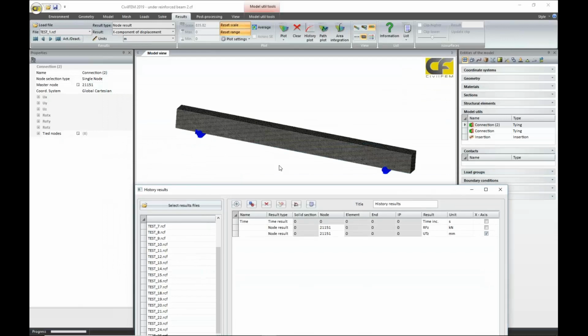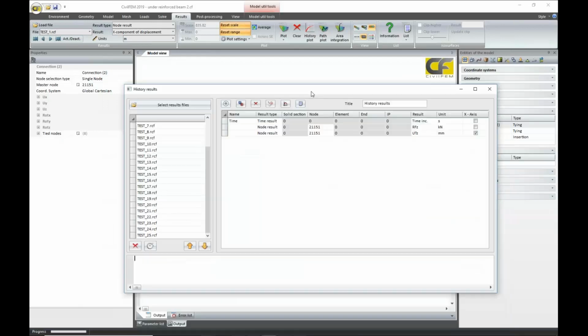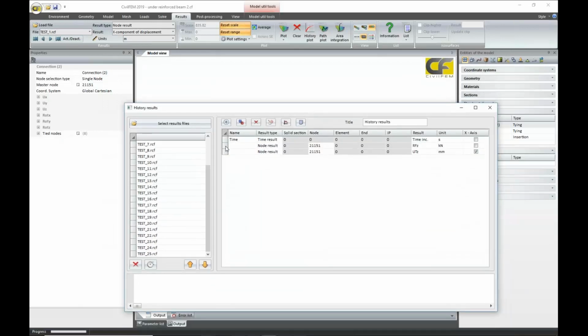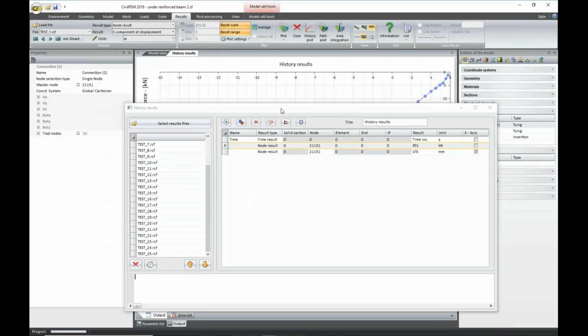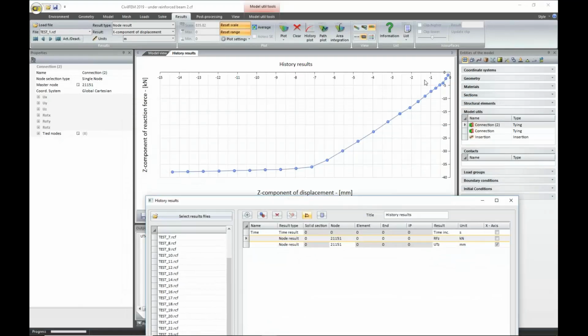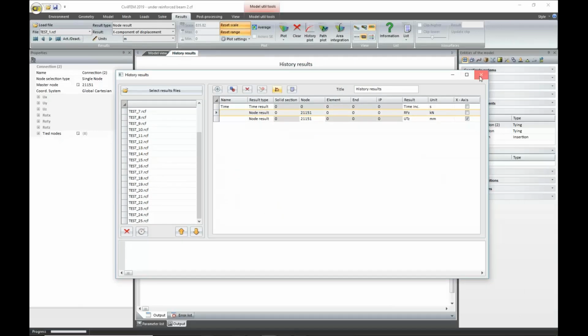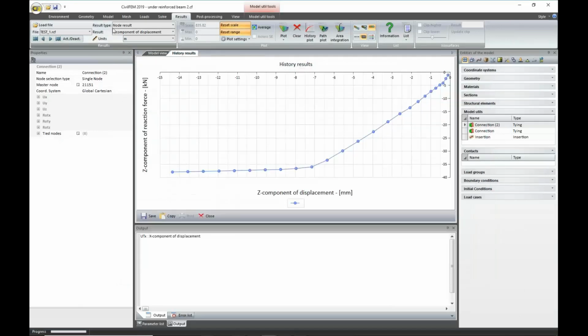And if we plot in one of these points a vertical displacement versus the load, we get this type of curve. We can see in this case we have a ductile behavior. At the first step here we have a modification, which could mean cracking starts, but mainly elastic behavior. And then we have a horizontal branch, a maximum load that we can apply between 35 and 40 kilonewtons. So let's see what's happening in the model for the last point.